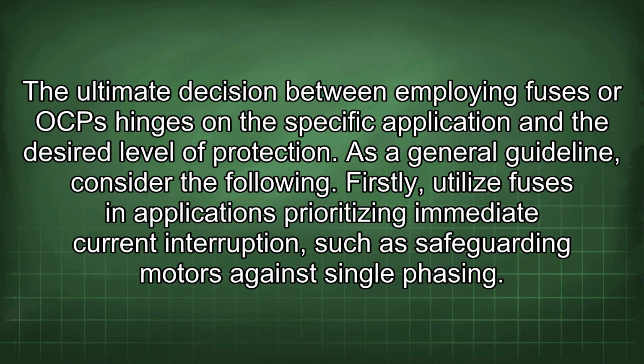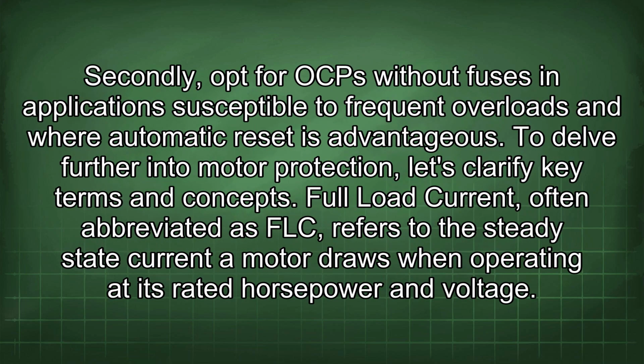As a general guideline, consider the following. Firstly, utilize fuses in applications prioritizing immediate current interruption, such as safeguarding motors against single phasing. Secondly, opt for OCP without fuses in applications susceptible to frequent overloads and where automatic reset is advantageous. To delve further into motor protection, let's clarify key terms and concepts.